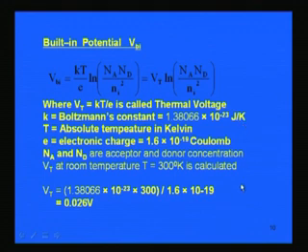So now if we consider room temperature, that is 300 Kelvin, which is generally done, all calculations are typically done at room temperature unless mentioned otherwise. So Vt, this thermal voltage, can be calculated using these constants, the electronic charge 1.6 times 10 to the power minus 19 and this Boltzmann constant. It gives a voltage of 0.026 volt at room temperature.